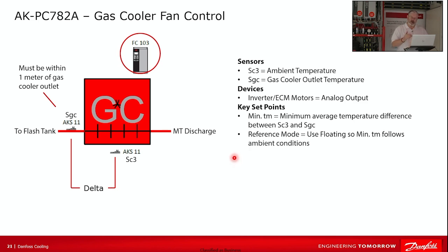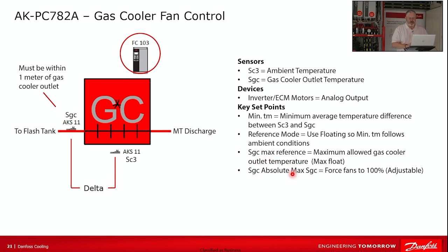We use a floating reference mode so that, as the ambient rises and falls, our 5 degrees difference just rises and falls with it. It's very similar to what's been done in the past with TD control. And then a couple of the key set points here.